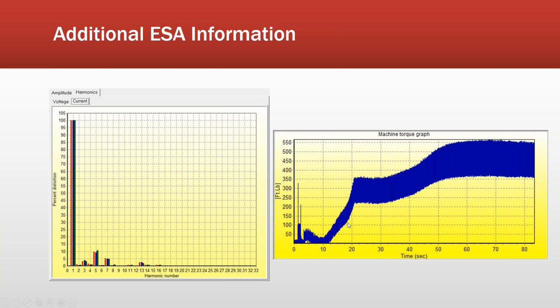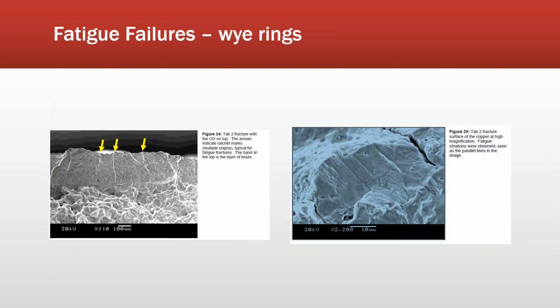Because of the location of that site away from heavier loads, quite a ways actually, and the fact that they hit a 500 kV line with linear capacitance, they actually had a very high SSR or subsynchronous resonance. It's referred to as torsional SSR, torsional interaction and control interaction in a wind turbine.